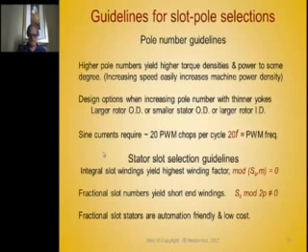For example, if I'm designing a machine in my consulting, one of the first things that I have to ask whoever's going to do the inverter, whether someone's going to design one from scratch or they're going to purchase a standard one, is what's the maximum number of poles they can stand with whatever PWM frequency they're allowed to use for transistor losses. So the PWM frequency has a lot to do with the number of poles as well.